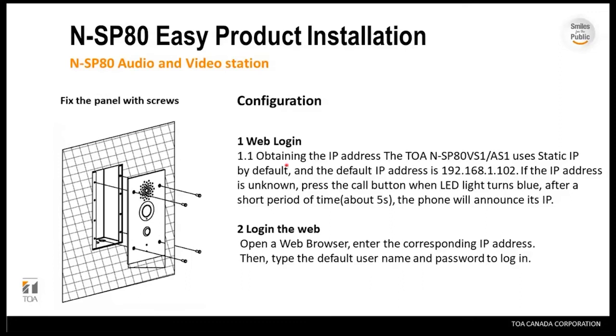Very simple to install, four screws and sheet mounted. Talk a little bit about communication of the SP80, obtaining the IP address from the video or audio. It uses a static IP by default. The default address is 192.168.1.102.